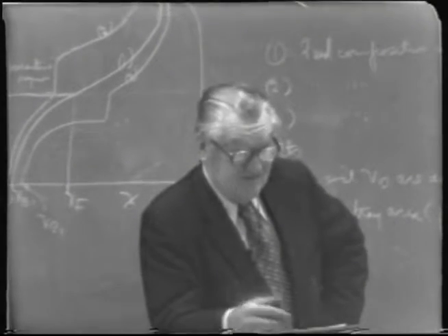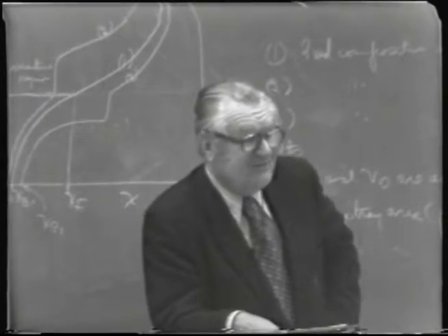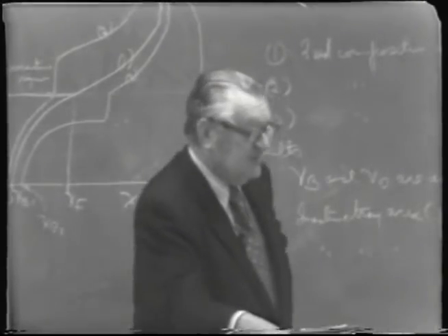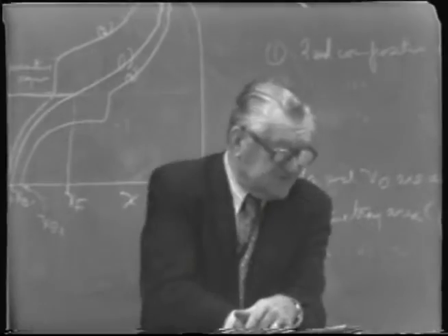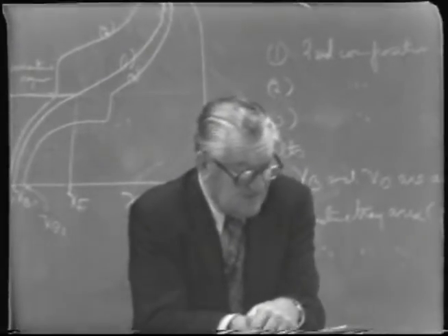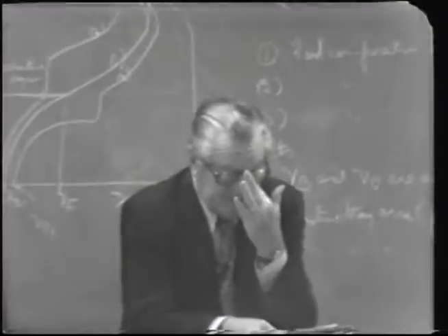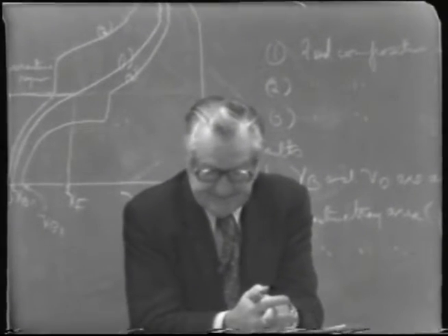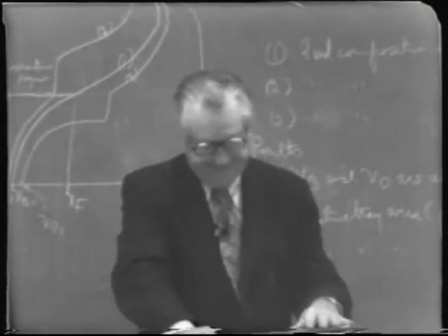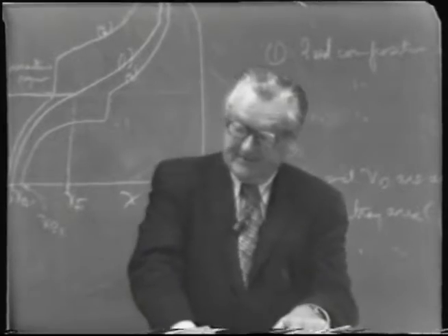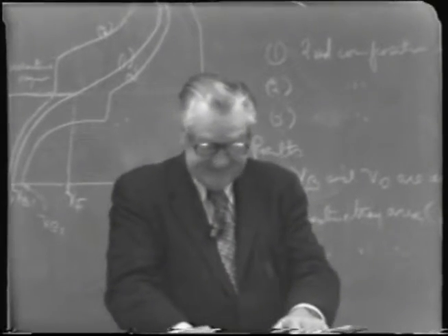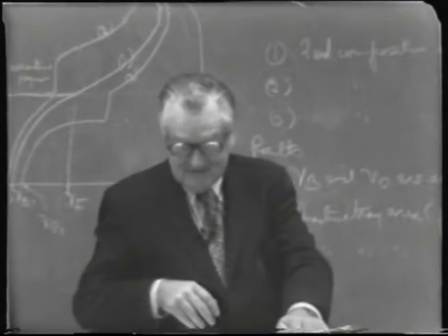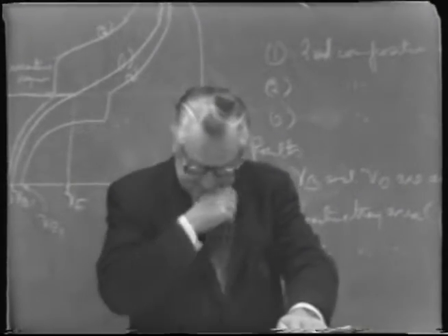There are some other reasons, however, in which there's some advantage to having more trays than you need, and that is in the treatment or separation of the volatile constituents. For example, the heads components, the acetaldehyde and ethyl acetate and diethyl acetal, if you have some SO2 present, which causes the alcohol and the aldehydes to react to form acetal.